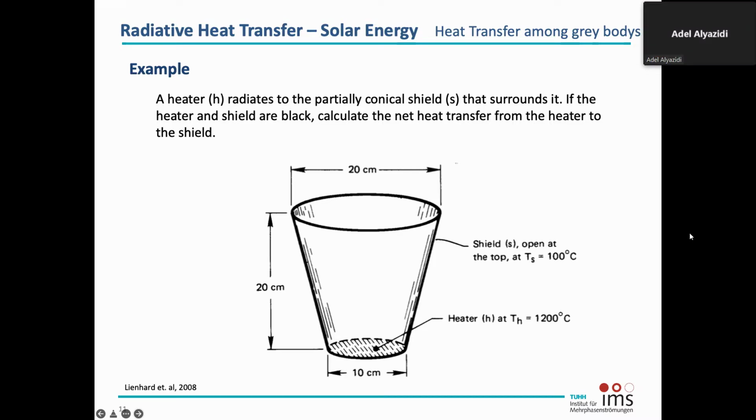You have a question. Any assumptions about heat transfer by convection? Yeah, good question. But convection, we don't take into account at this point, because we are interested in the radiation of heat from this point to that point, or to the shield, and we assume that this is, let's say, shielded also against convection from the outside. So what we take into account here is only radiation in this case. But it's a good question. Here we just want to know what is the influence of radiation.